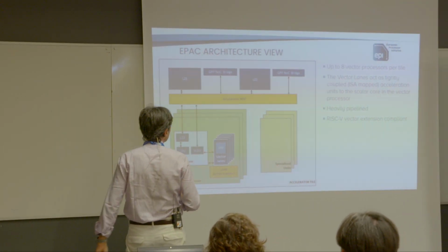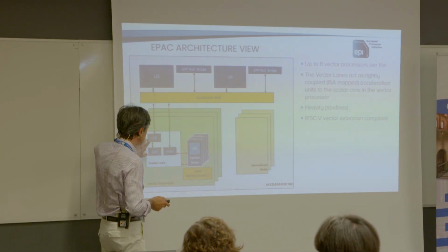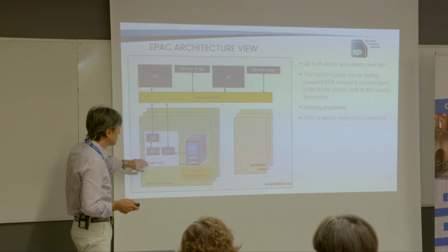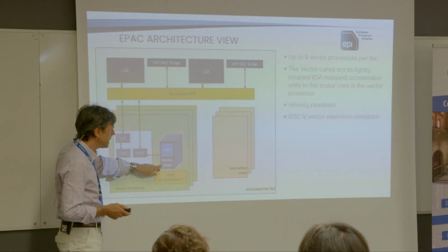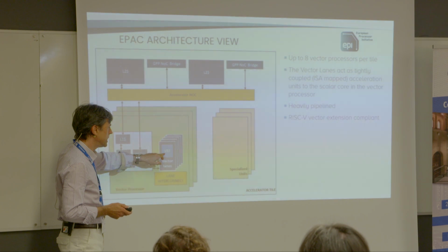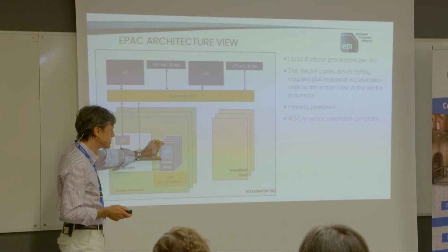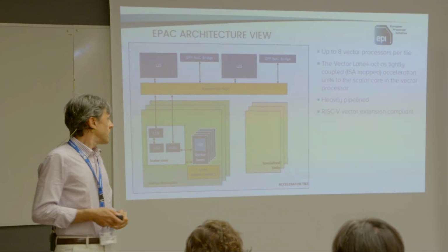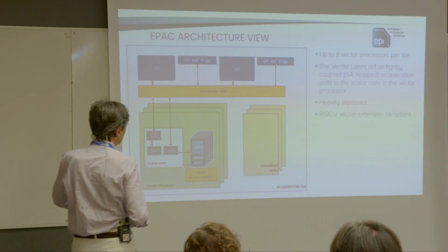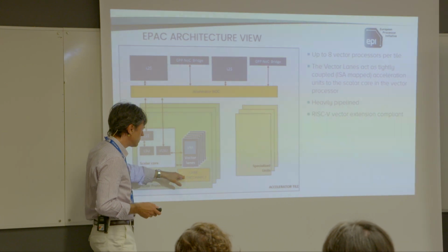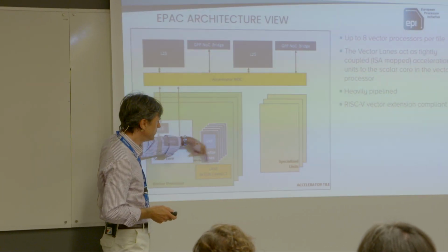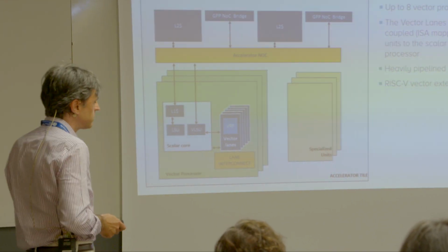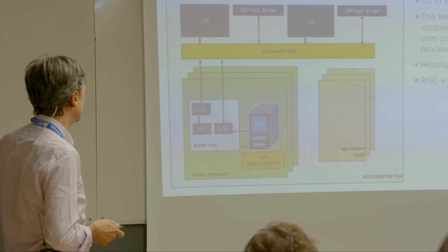And the internal of that is based on a scalar core. This is a RISC-V scalar core controlling vector lanes, which are the functional units equipped with the portions of vector register files operating directly on the vector data. Of course, we also have a lane interconnect, and we're working a lot on that because we need to move vector elements also among the lanes, which is a relatively complex problem, technically speaking.